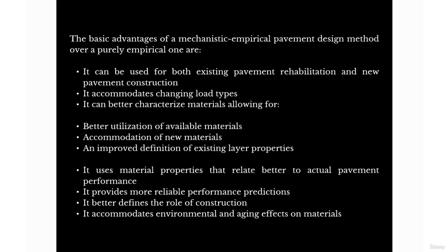This also improves the definition of the existing layer properties, because remember, you can go and use that deflectometer to see exactly how the existing road is performing. So that is why the mechanistic empirical method is best for situations like that.